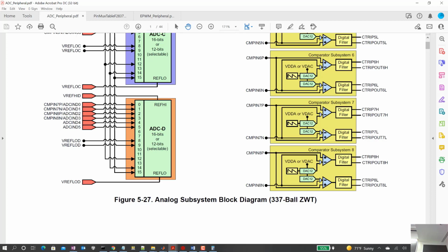And so when companies do this, they always have to do some tricks, I'm sure, to get these ADCs working well. I'm sure they've gotten those tricks figured out more and more as years have gone by. But still, I bet that's some reason why they don't give you all the I/O pins. So in other words, they're leaving this up for future processors. Maybe in future processors there will be something connected to channel 6 and 7 and 10 and 11 or whatever. Okay? But these happen to be the ones.